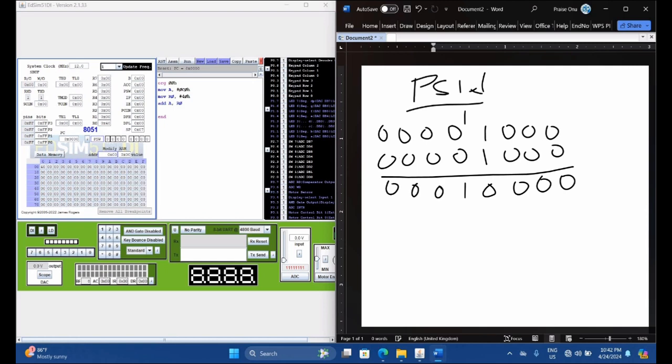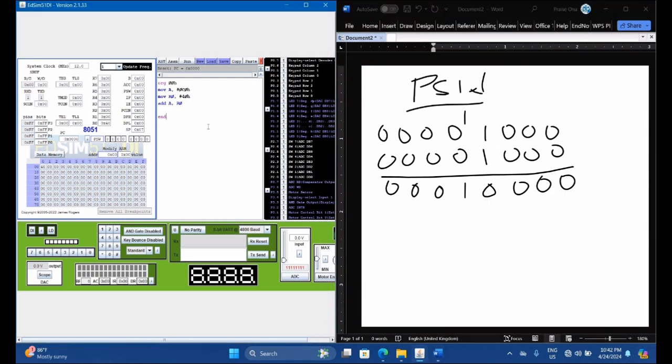So what this means is this bit is our third bit and this is our fourth bit. So from the third bit to the fourth bit, there is a carry of one bit. So with that, our auxiliary carry indicator would come up. So we can also demonstrate that and see. And if you convert this to binary, you also see the value in binary.